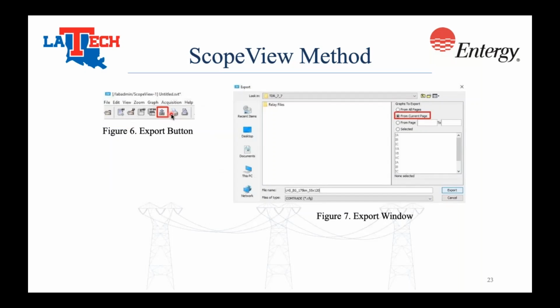This depicts the export button, which is seen at the top of the ScopeView signals window. And when you click that, the export window opens up. Be sure to only save the current page, so the 2 pages correlate to 2 different files. Then always give it a unique name. I typically like to give info about fault type, location, line length, and any other special circumstances to avoid confusion, and so I can go back to the files for reference or future simulations.